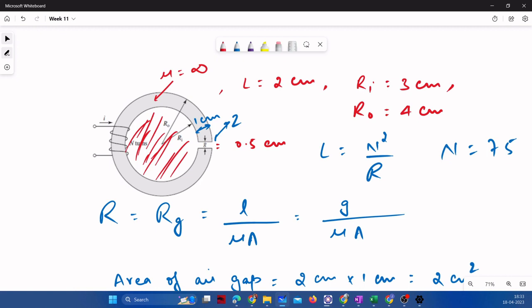If you want to introduce another shape apart from the existing shapes of toroidal core or rectangular core, then those cores will be more efficient or more optimal wherever you can incorporate a high number of turns within the given area. Then that core would be considered an optimal choice.